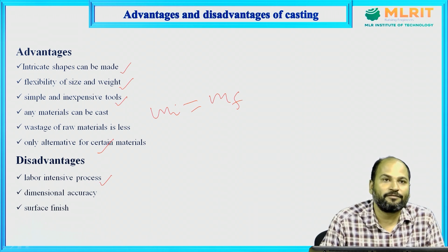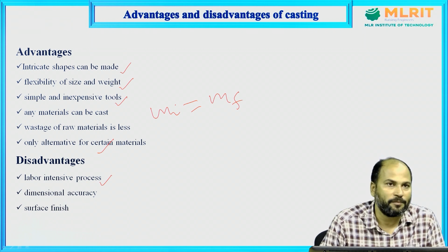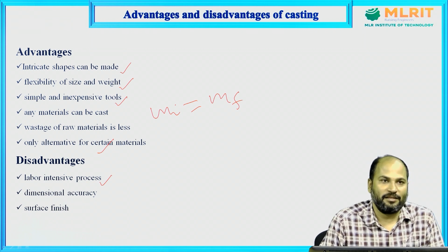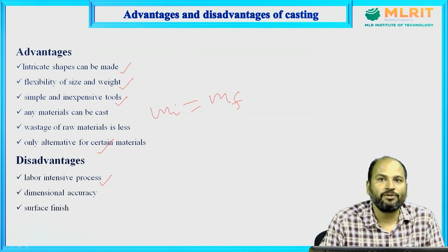Also the size of all the sand particles will not be the same, so to bring them to equal size, we will have to crush it. After crushing we will have to use a sieving operation to sieve all the sand particles. After that we have to prepare the sand mold, so we will have to mix water and some additive so that the sand mold will be prepared. That's why sand casting is labor extensive, meaning you need more hours to carry out the process.